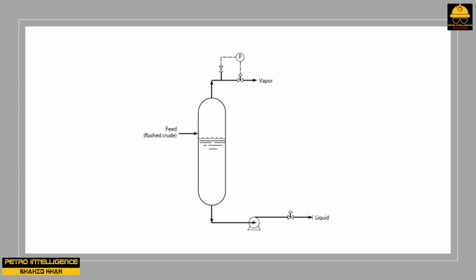But this will take time. If the residence time of the liquid in the drum is 10 minutes, then it will take 10 minutes for the lighter liquid to reach the suction of the pump. During this 10-minute interval, the liquid flowing into the pump is the older, heavier composition.